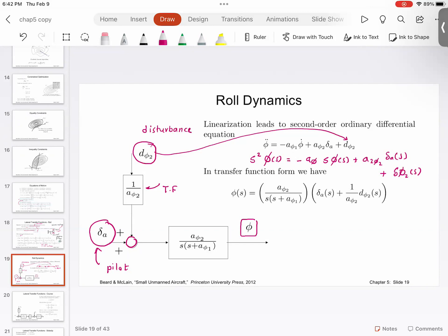I will repeat this once again. Once you go to industry, you will realize how powerful this technique is. What I did was take all the nonlinear, unmodeled dynamics and treat them as a disturbance. Whether that disturbance is linear, nonlinear, quasi, or stochastic doesn't matter. It's a disturbance, and I don't want it. So I found the transfer function that is acting on the disturbance, and I see that this disturbance gets fed to the actual linear transfer function I'm interested in.